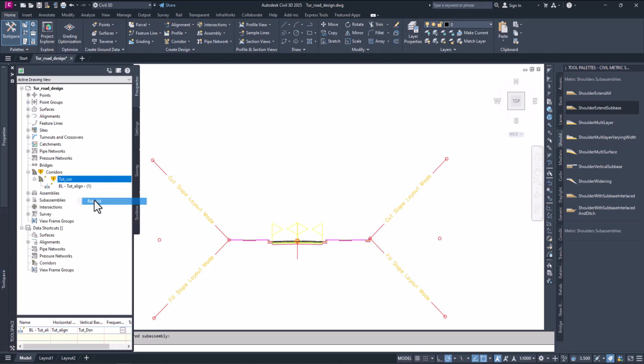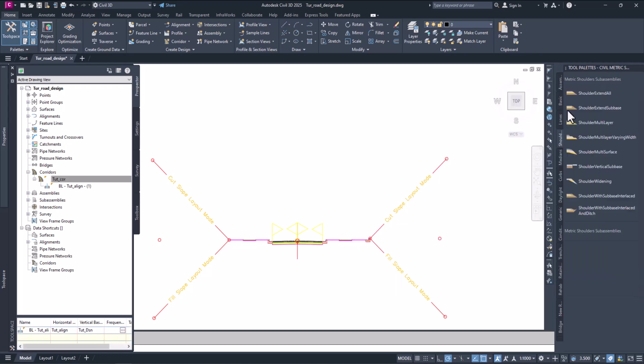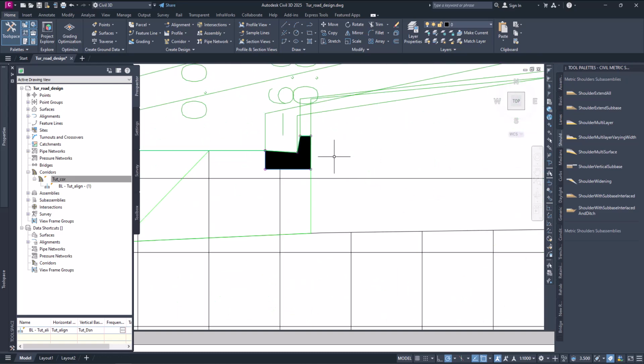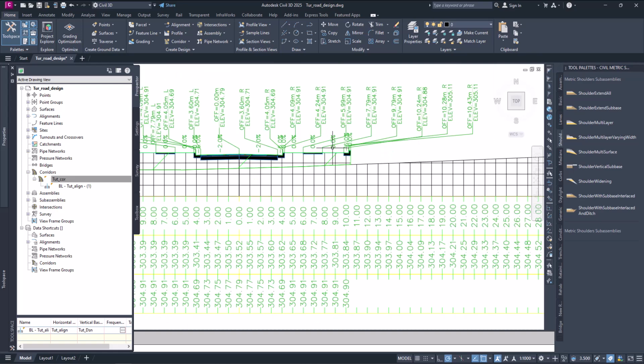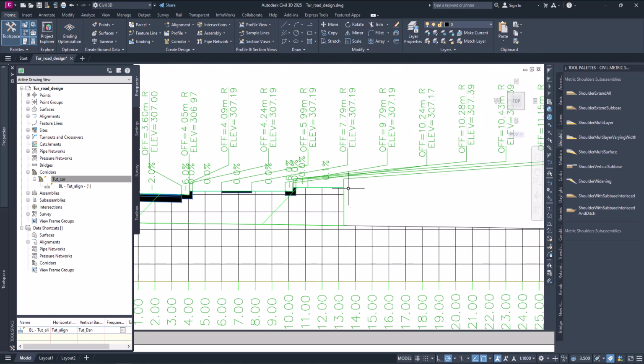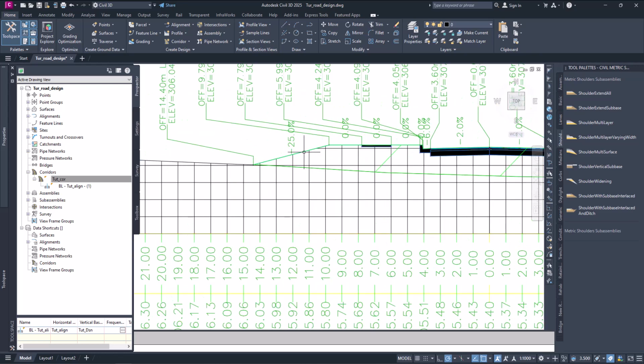Now let's update our solution. Let's rebuild it. Now you should see some error, and why is that? Let's check and resolve it. The error you will see here is that nothing is there. Let's find a location where we have fill. You don't see any daylighting here. On the other side you can see the daylighting and the slope, but here you won't see any slope.